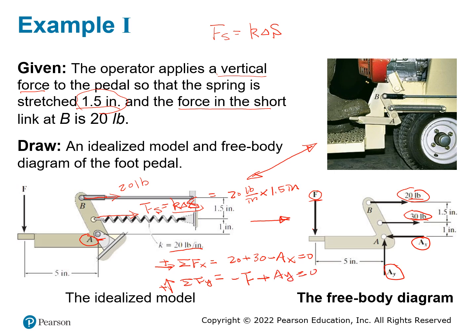Okay, that's only two forces in the y direction. Are there any other equations we can use? How many unknowns do we have? We have 3. These 3 are unknown, and we only have 2 equations now. We need a third equation. The third equation is going to be the summation of the moments about a reference point of your choice. I will use point A because it will help me eliminate these two, so I don't need to do any calculation for them. And this has to be equal to 0.